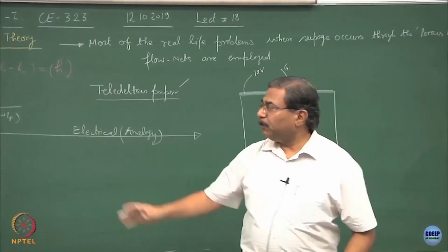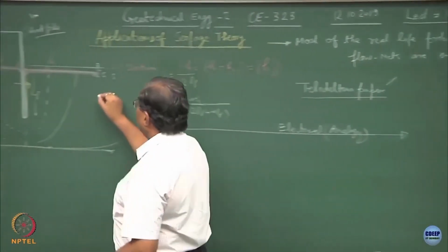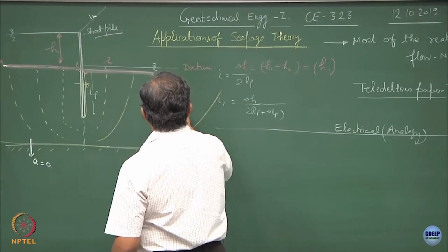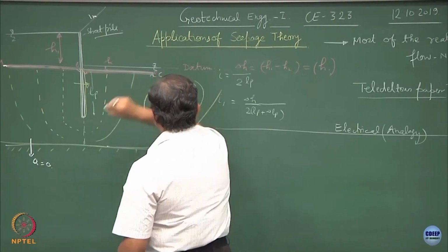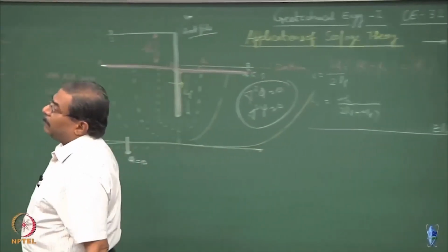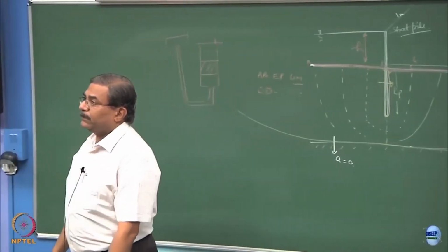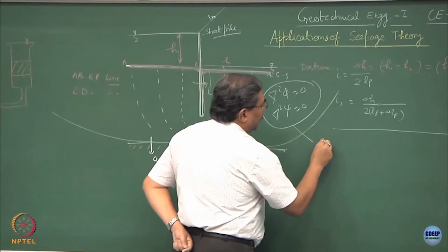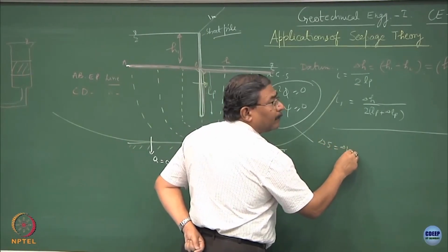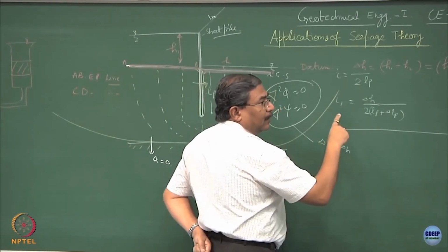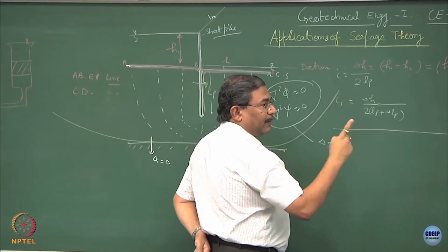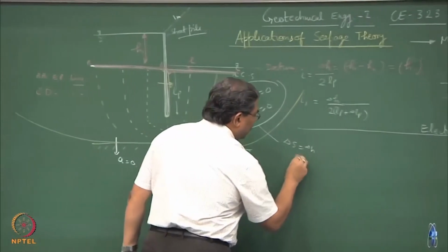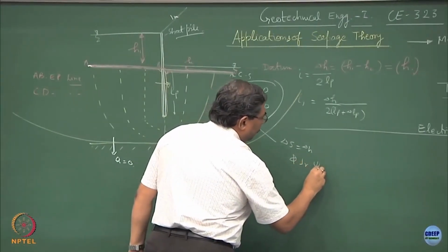Either I should be doing solution of del square phi equal to 0 and del square psi equal to 0, which we did yesterday in the classroom, and mathematically I can develop a flow net. What conditions you have to maintain? If you remember, delta S equal to delta N, square, curvilinear square or a linear square, clear, and psi and phi are going to be perpendicular to each other, got it.